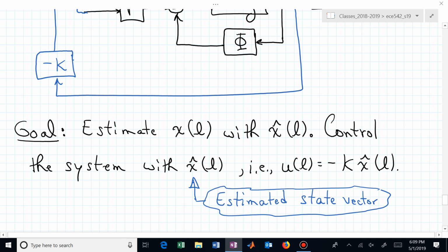So this is the more direct way of explaining, but if you want to go further, the next process might be, oh, let's build a reduced order estimator. In this case, how big is your estimator? Now you've built a 10th order estimator. If you do a reduced order, maybe you only have to estimate 6. So you don't have to have as much computational machinery happening if you do a reduced order estimator.